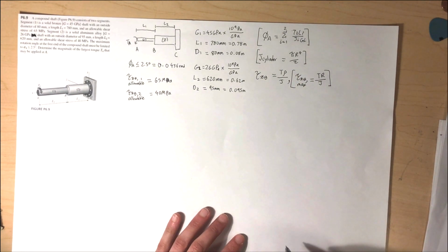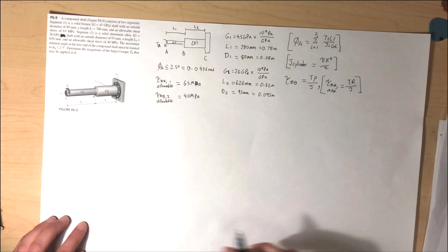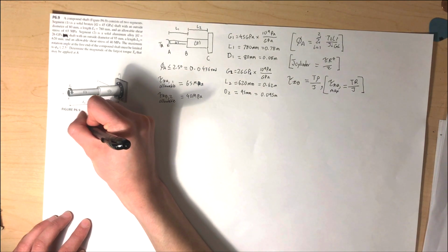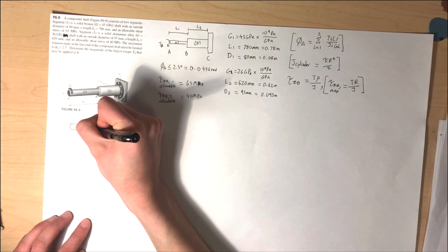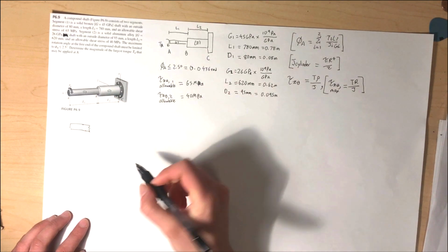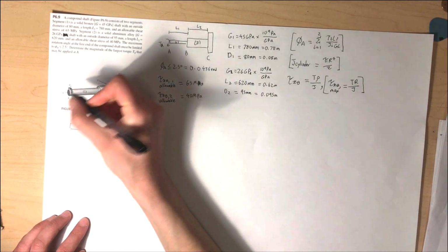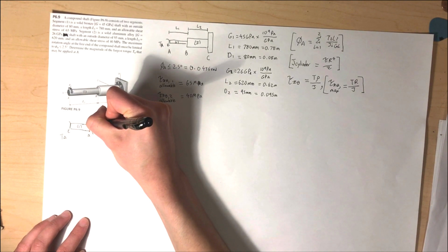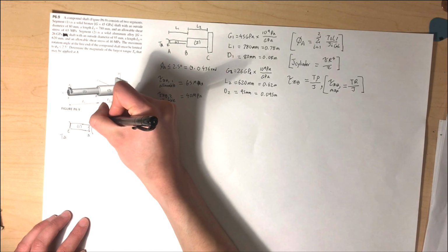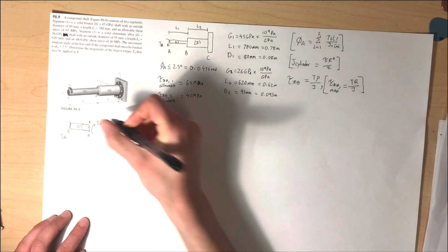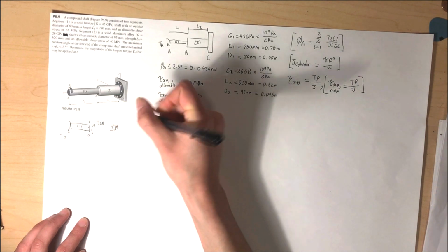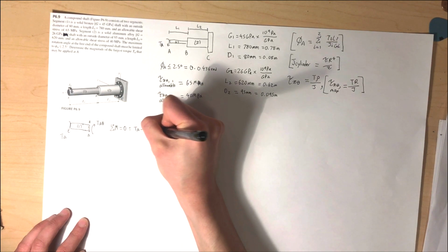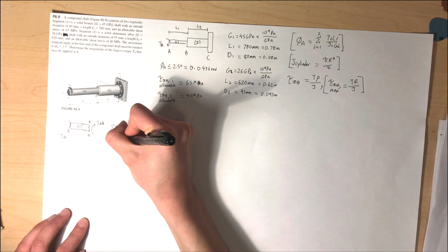So our first step is going to be calculating the internal loads in each member, and this can be done by taking a cut in each and evaluating an equilibrium equation. So if this is member 1, we know we have TA here, and that there must be a moment acting here, which we can call TAV. By equilibrium equations, we know that net moments are 0 equals TA minus TAV, and therefore TAV is equal to TA.